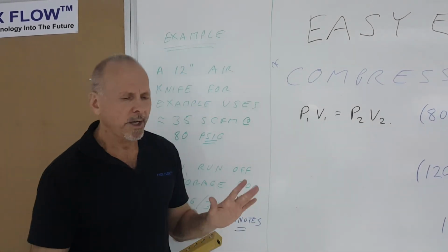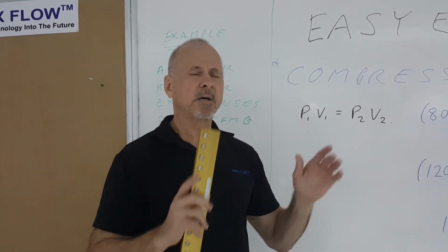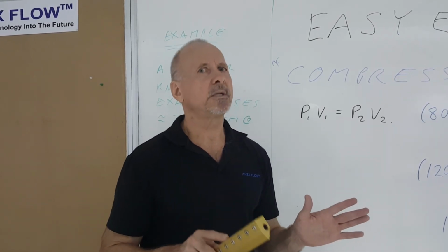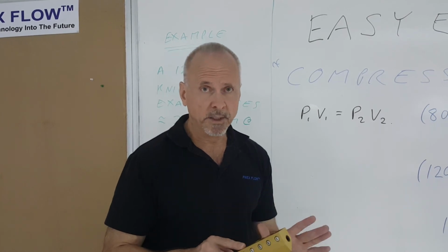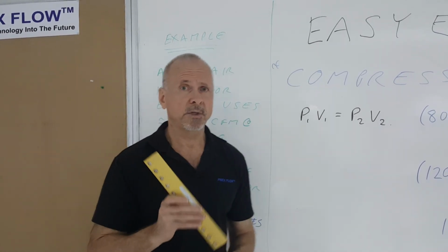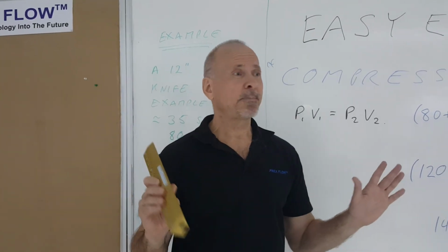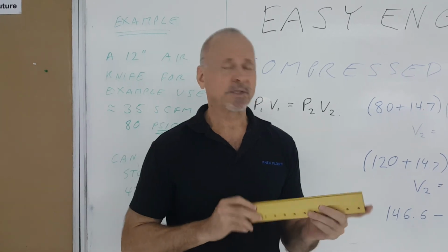So when you're comparing the use of compressed air for blowing off versus a blower system for blowing off, recognize the effect on energy reduction in using a compressed air system for intermittent use and also the actual pressure that you need to use. So next time, another topic for Easy Engineering will be another topic concerning compressed air.